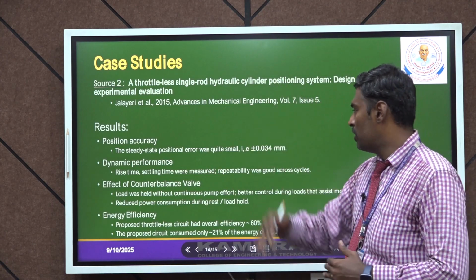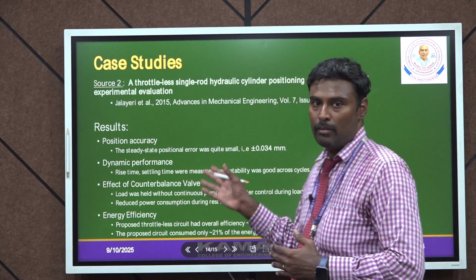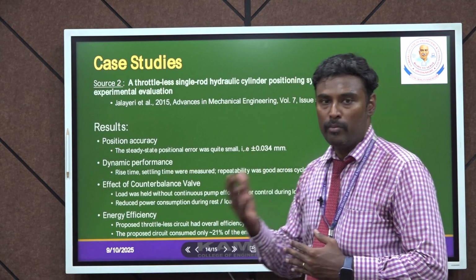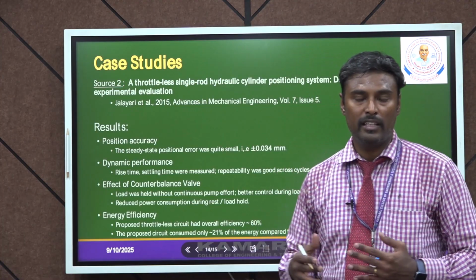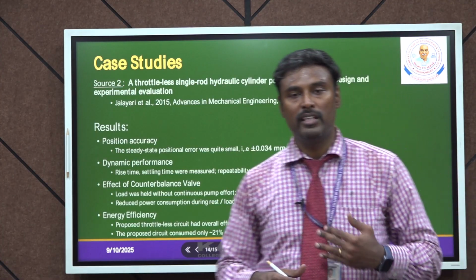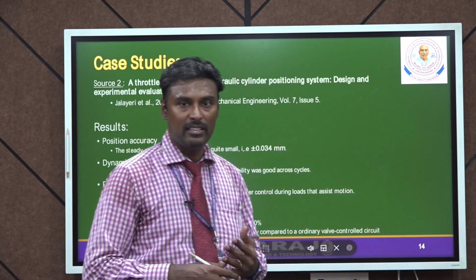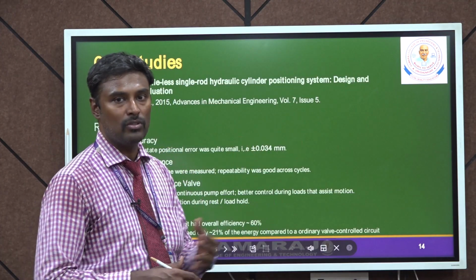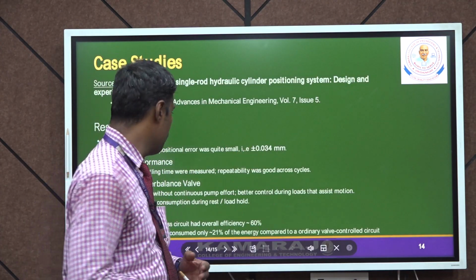So the rising time and settling time were measured periodically using some pressure transducers, and the repeatability was good across so many cycles because the experiment has been conducted for various cycles, various times. So based on the various response times, various cycles, and varying conditions, the dynamic response performance is also quite good based on this proposed circuit.